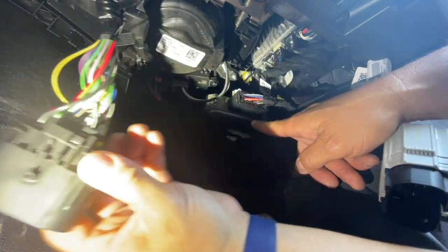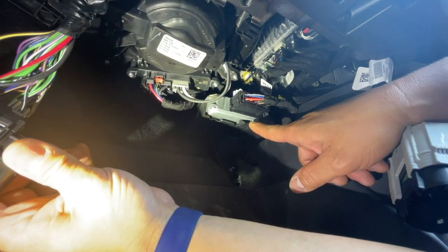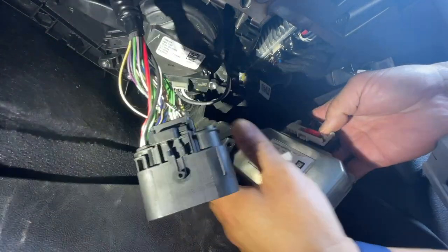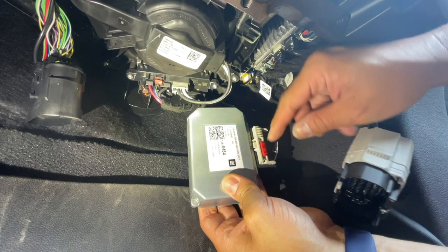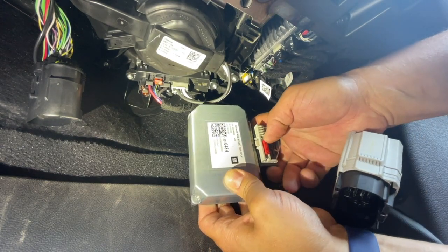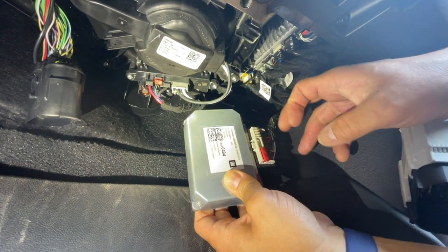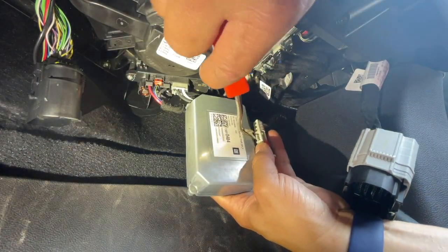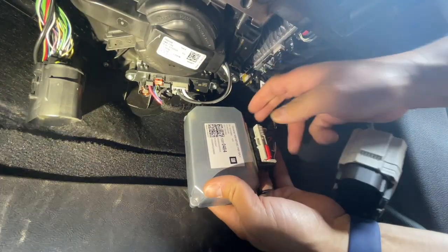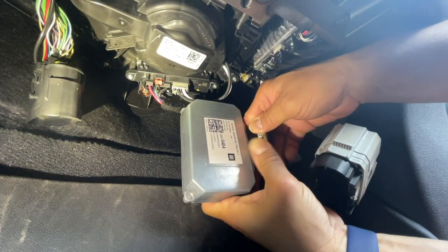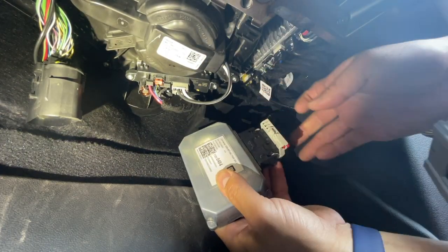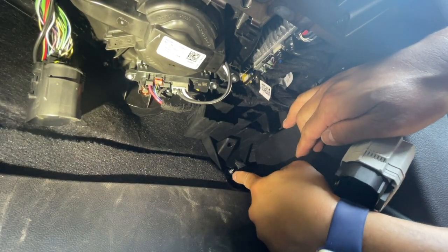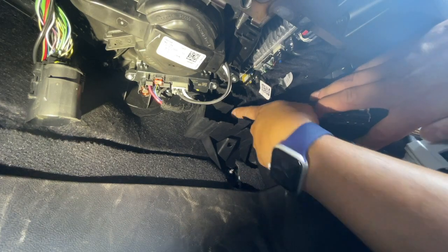So just push down on this retaining clip here, and the whole thing slides out. To unplug the inverter connector, you're going to slide this red CPA down, just like that. And then using a screwdriver, you're going to lift the tab here, and that will allow you to rotate the white lever rearward, just like so, and then you can unplug. We're going to use a 10mm socket to remove the bolt for the bracket here, and one up here.